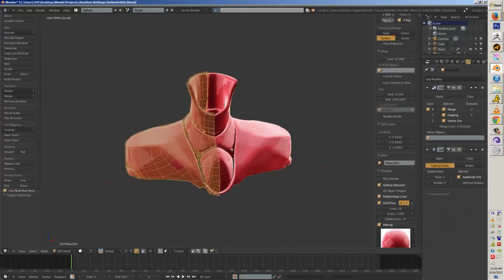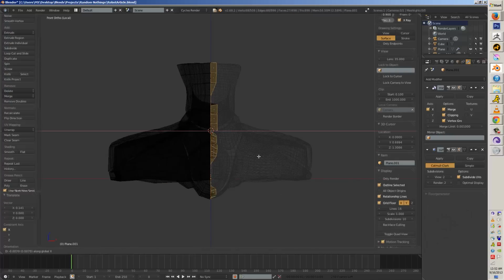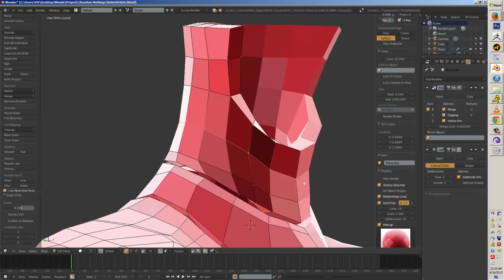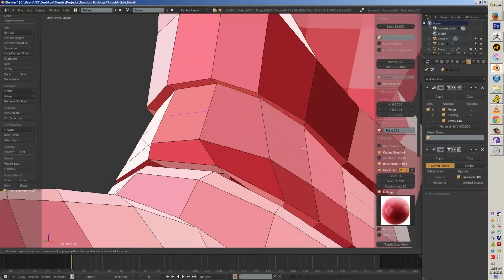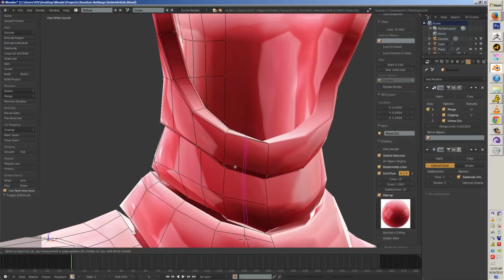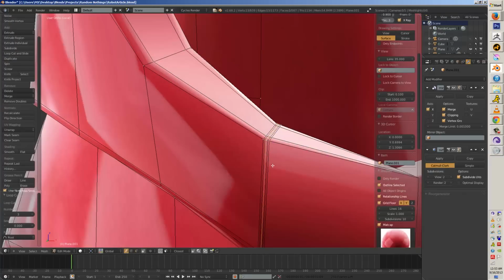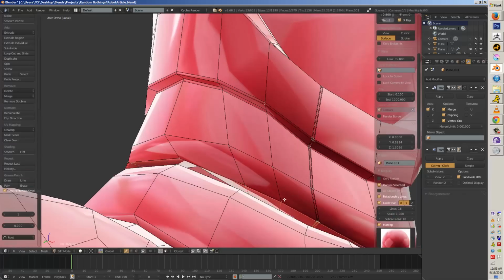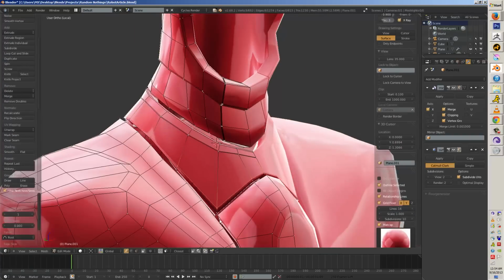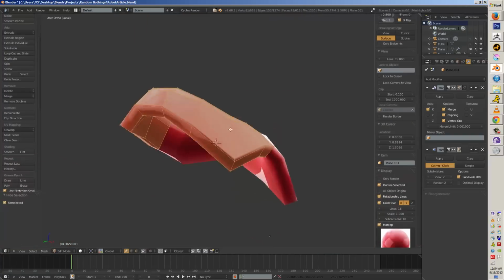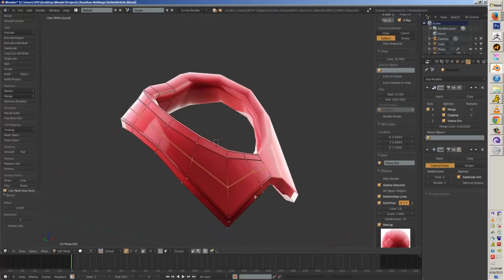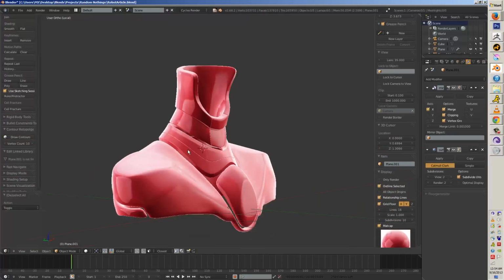But for the body, might as well just use a solidify, and slap those edges on the mirror and delete the faces. One of the things with using solidify with the mirror is that it will put faces in front of the mirror, which will put a nasty crack in your model, and especially with the subD that gets annoying. So in order to prevent that, you want to do as I do and just select it and delete the faces. Don't delete the vertices, you might find yourself losing more geometry than you want.